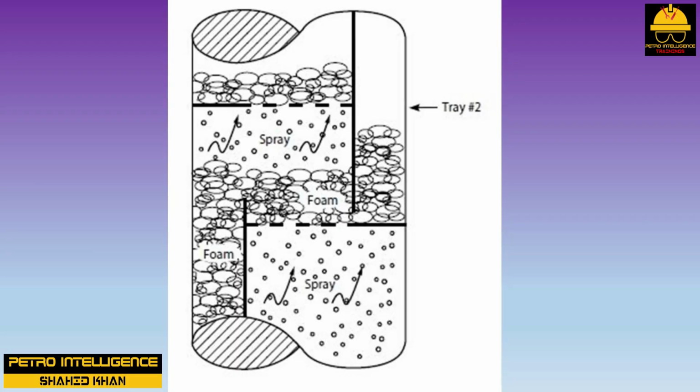Jet flood. This is a realistic picture of what we would see if our towers were made of glass. In addition to the downcomers and tray decks containing froth or foam, there is a quantity of spray, or entrained liquid, lifted above the froth level on the tray deck. The force that generates this entrainment is the flow of vapor through the tower.